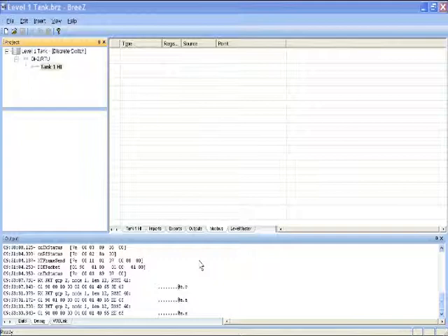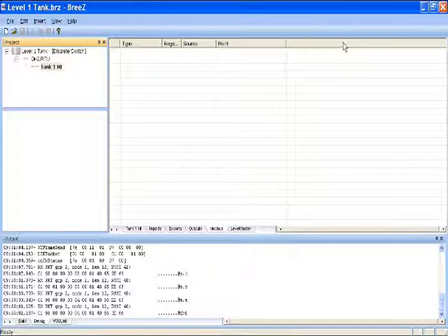Now I have moved my configuration cable back to the DH2 and have my debug tab open in my output window. Notice the RX packets coming from group 2, node 1, with a received signal strength of 41, 40, 40. You notice a packet comes out every time there is a state change of said switch. I have switched the switch 3 times. Now we know the switch is working. We know that data is being sent and confirmed in debug at the DH2. We are now ready to set up the Modbus master.